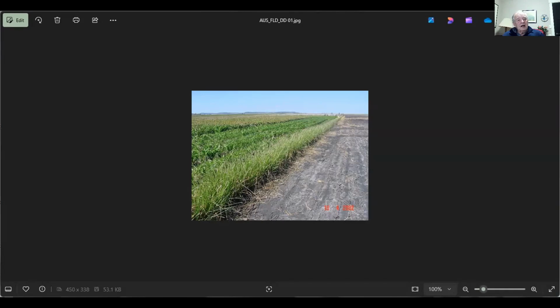But the key of all this is to plant a proper hedge. There are far too many people who use vetiver, and they plant vetiver too far apart in the line. If you plant 2 feet apart or 1 foot apart, you don't get a good hedge. As soon as you plant maybe 15 centimeters between plants, you get hedges like this. And these are fantastic hedges. I'll show you, there's another, well, anyway, I could go on talking for hours on this.